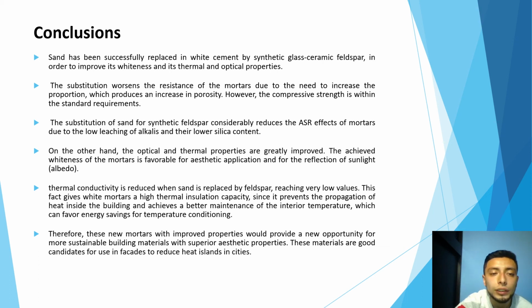The high whiteness of the mortar is favorable to aesthetic application and for the reflection of sunlight. Thermal conductivity reduced when the sand is replaced by feldspar, reaching very low values. This fact gives white mortars high thermal insulation capacity, since it prevents the propagation of heat inside the building and achieves better maintenance of the interior temperature, which can favor energy savings for temperature conditioning.